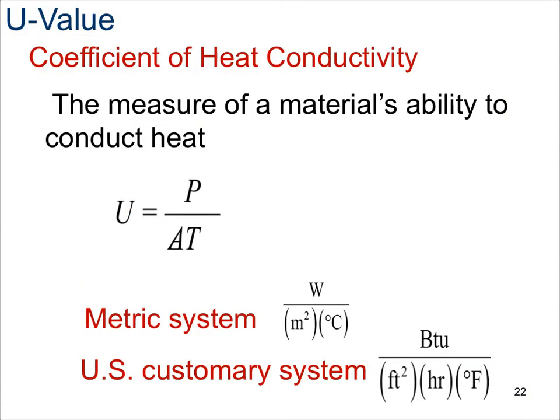One of the most important material performance measures is U value, also known as the U factor, which measures the insulating characteristic of that material and how much heat flow or heat loss occurs through the material due to the difference between indoor and outdoor temperatures. U values can tell you how much an insulated material will hold in heat or cool air.